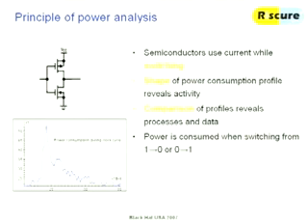And that's probably way before the next clock cycle even. And then on the next edge of the clock, or maybe the next up edge, they do their process again. And what you see is a profile like is drawn in the picture. You get a kind of spike at the start when every gate starts to be active, and then slowly it dies out. And the profile of that measurement actually says something about the number of gates that have been switching. And if your CPU is doing something related to a program or data, then that power profile will be related to that data. So the question is, how can you get the information out of there?